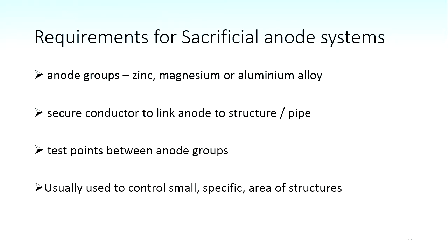Okay, so you rarely use a single anode, you usually use multiple anodes on your structure. Zinc is used in pure form quite often. Aluminium is usually used as an alloy, so it's quite often some sort of aluminium zinc indium alloy, or some other mix, sometimes magnesium aluminium alloy.